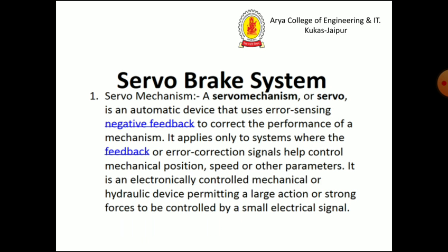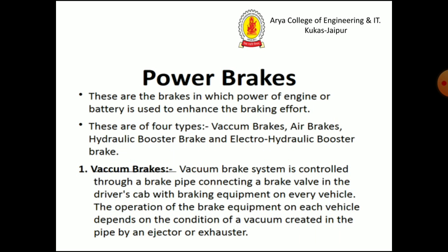Servo brake system, in which a servo mechanism or servo is an automatic device that uses error sensing negative feedback to correct the performance of the mechanism. It applies only to systems where the feedback or error correction signal helps control mechanical position, speed, or other parameters. It is an electrically controlled mechanical or hydraulic device permitting large actions or strong forces to be controlled by a small electrical signal.